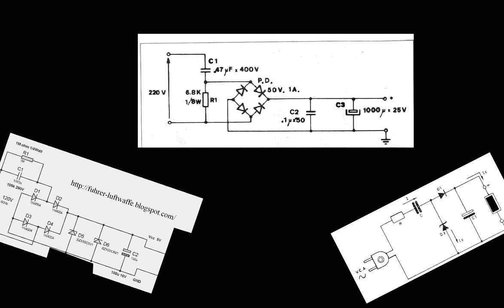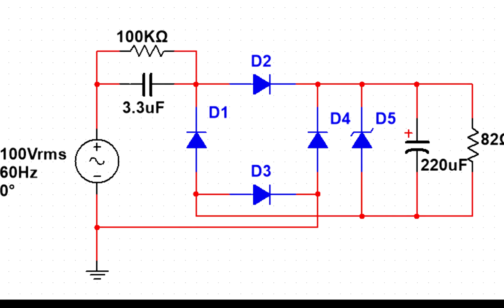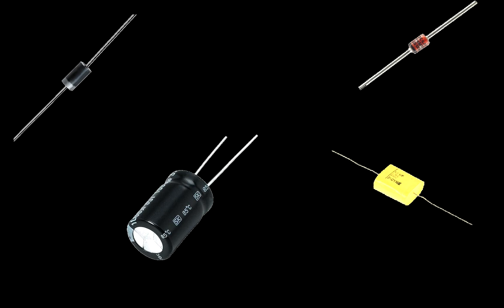The team started with the research of an established circuit diagram using the mentioned elements. Once the team got the diagram, simulation began. Using Multisim software, the team implemented the diagram and then made some tests using virtual tools given by the software. They proved that it works using rectifier diodes that deal with at least 100 volts, 5.1 volt Zener diodes, resistors and capacitors.